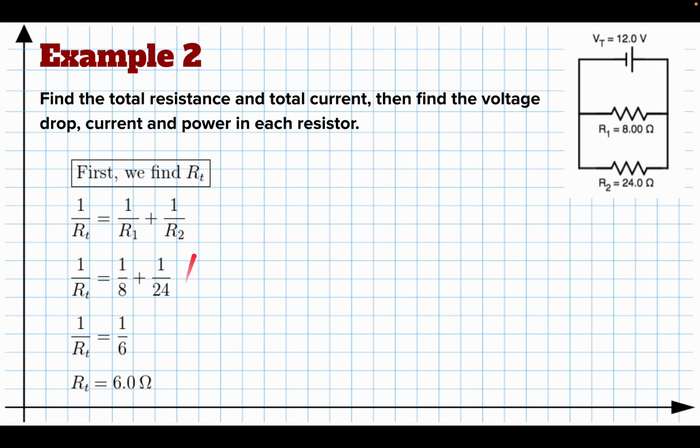Okay, now, quick note, when you solve this for R total, this is not R total, this is 1 over R total. To get R total by itself, you've got to take the reciprocal, or take 1 over the left side. So in order to find R total, you've got to take 1 over the right side. So don't write this down in your toolbox, because that's not the answer you can start with. But when you solve this equation for R total, it's going to look like this. It's going to be 1 over the quantity 1 over R1 plus 1 over R2. So that's how you're going to find the total resistance when it's time to actually get the number, okay?